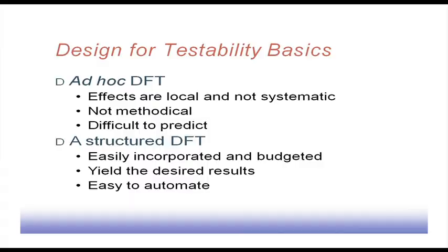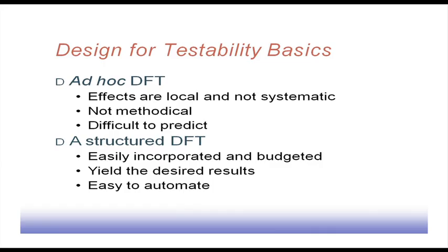So, the test engineer can be sure that I will have this much extra that I can incorporate into the design to yield the desired result. Naturally, if all those features are incorporated, then possibly I will be able to reach my desired level of yield, and automating the whole process becomes easy. For example, if I have the scan chain, then I can very easily put the desired values at the scan flip flops. That way, automation becomes easy.